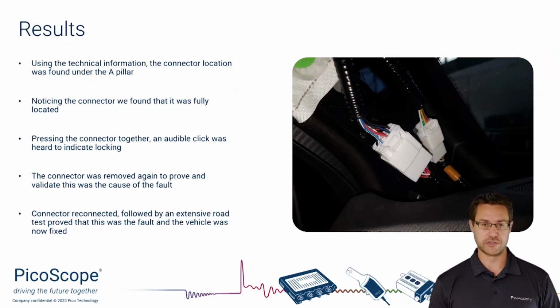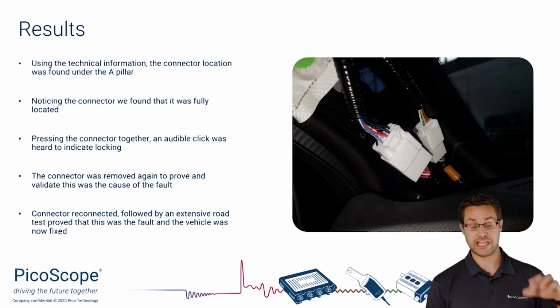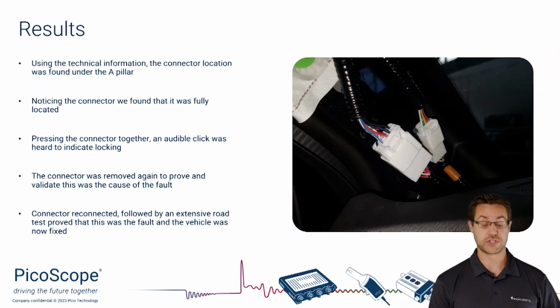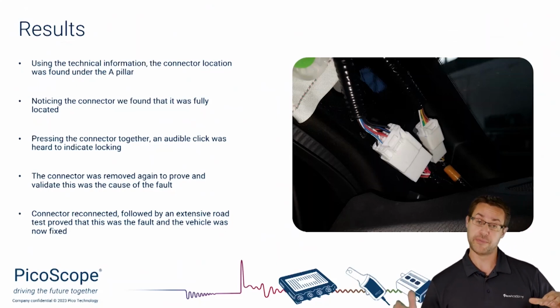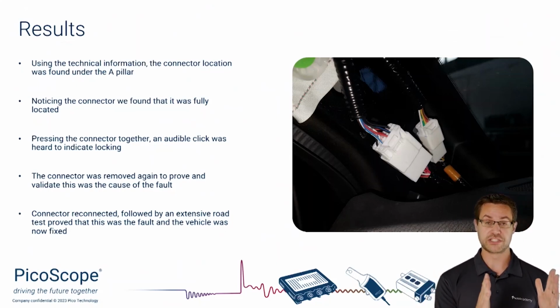So how can we start to move in closer to it? Well, the easiest way is to find additional access points to actually start measuring at. So we then moved our channels A and B slightly closer, where we got onto the DC-DC converter and another control module, and then we moved from our instrument cluster and moved into the network slightly.